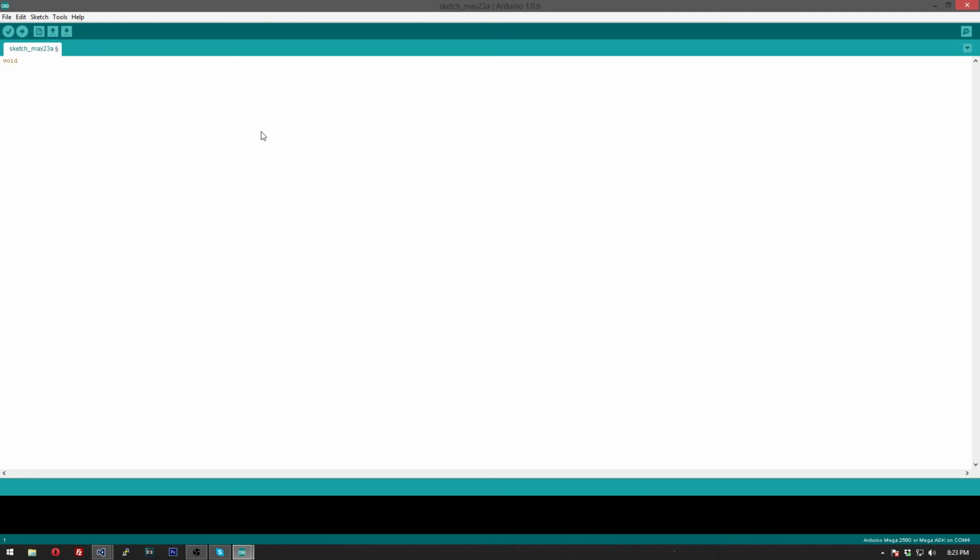So let's do void setup, and this runs once, and we're gonna do Serial.begin. Let's go ahead and do 9600, because that's what we set within C#. So they're both running at 9600, so they're compatible with each other. Once we have that set, let's do pinMode. We're going to be controlling the LED through pin 13, so let's do 13. We're going to set that as an output.